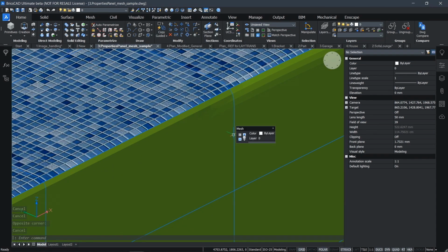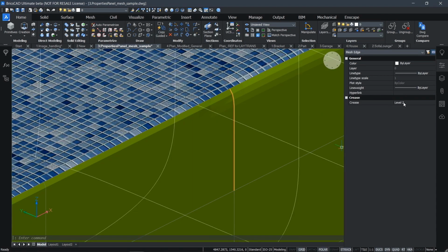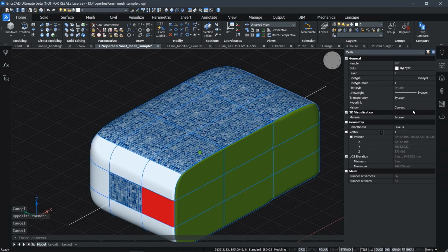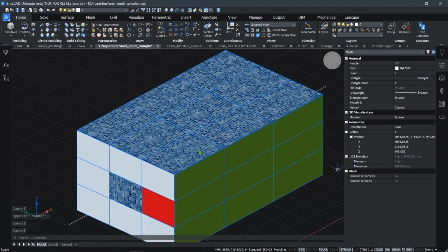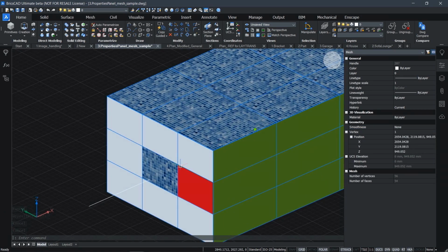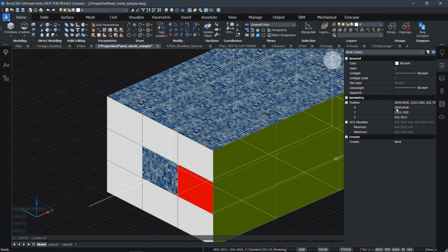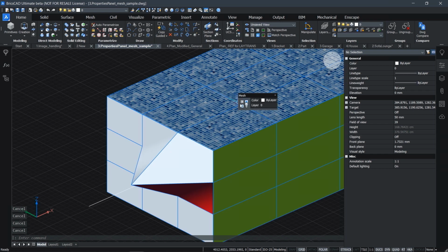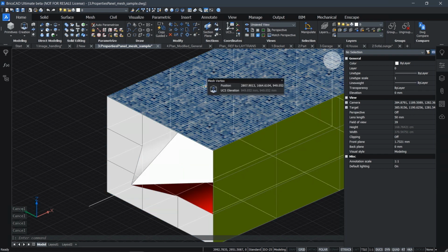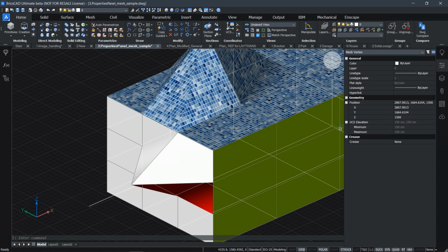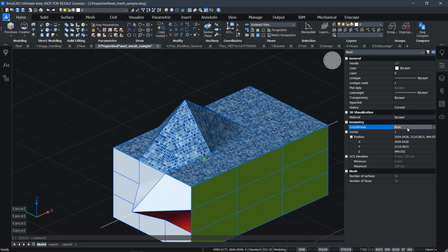Zooming in here and changing the smoothness property. So it gives you a lot of control over the object that has been imported. And let's go a little bit crazy even. Let's set the smoothness property to 0, to none, and pull out a point, and at the top we'll pull out another point, and then we'll switch on the smoothness again, and we've completely remodeled this imported thing in a couple of seconds.